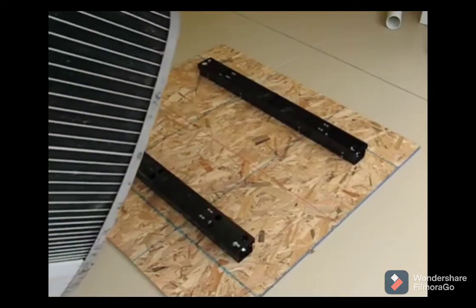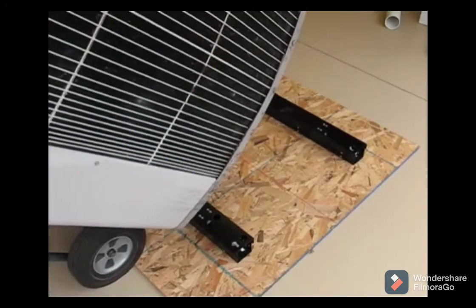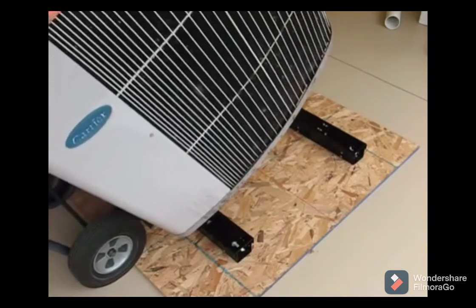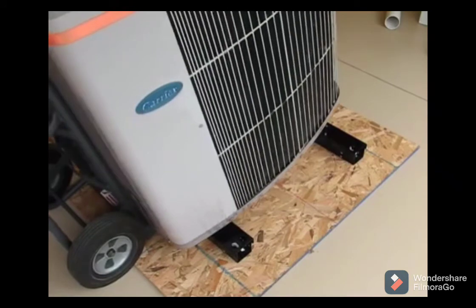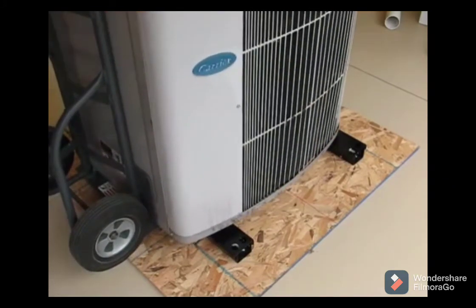When the isolators have been properly placed and fastened, place the condenser gently on top of the 2 isolators, centering the unit appropriately. It is recommended that 2 people be involved with the placement of the condenser to prevent possible injury. Ensure that the isolators are properly placed on any dimple features in the base of the condenser.